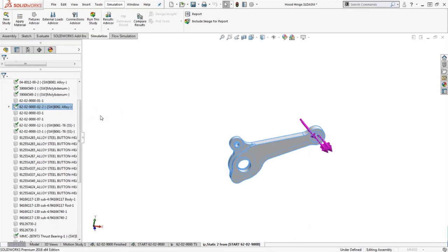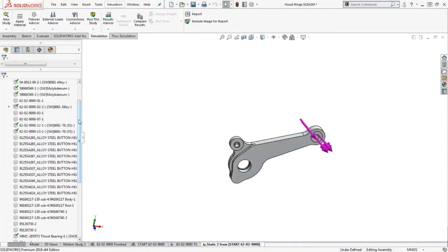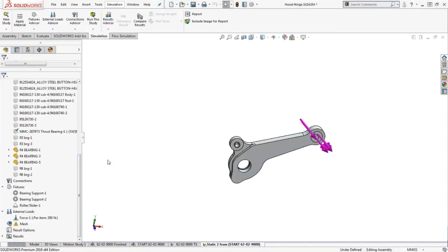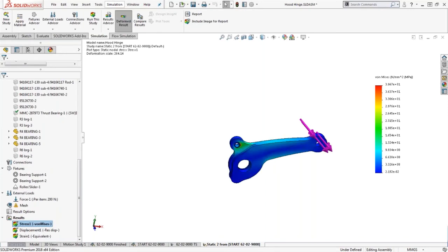And if we look at the yield strength of it, in terms of MPa, you see that my yield strength is about 55 MPa. So what I really just want to check for is that at the current setup, the current fixtures that I've defined, it's fixed at these holes, and then apply the force here. I want to run the analysis, and when I get my results, you see that I get an overall stress after it loads up here, hopefully under the yield strength of the material.